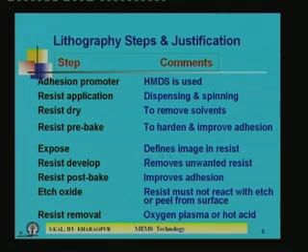Okay. Next step is expose, where you define the image in the resist. After that is resist develop, which removes unwanted resist. So, in the developer solution, as I mentioned, the soft region will be washed away in the developer solution and the hard region will remain. So, that removes unwanted resist in the developer solution.